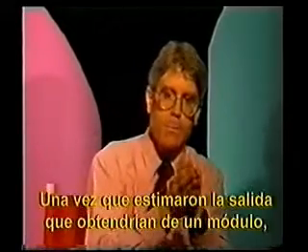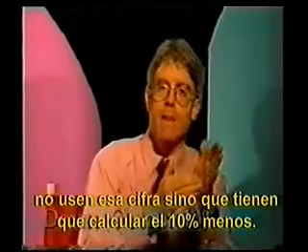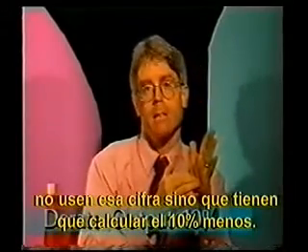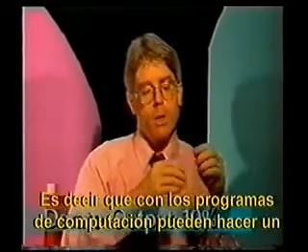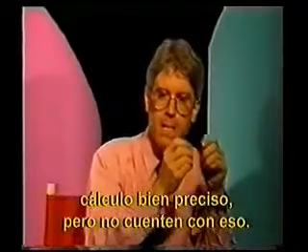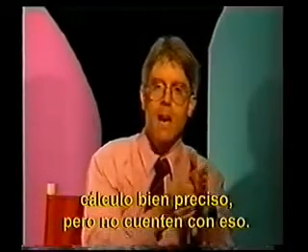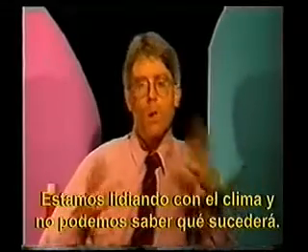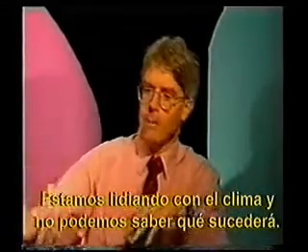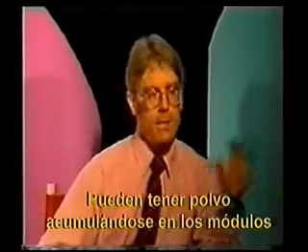Once you've estimated the output that you get from one module, don't use that output. You should derate that output by about 10%. In other words, we can calculate with our computer programs to the nth degree, very precisely, an estimation of what the module will give. But don't count on that. We're dealing with the weather. You don't know what's going to happen. You could have a bad month, a good month, a bad year, a good year. You don't know. You could have dust and so on